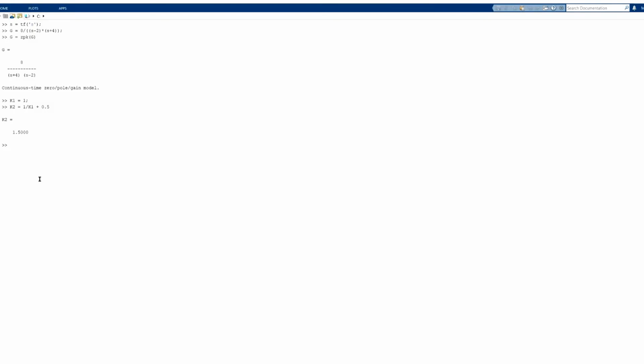But if I move on with this one, then I have actually the situation for A. So I now have A equal to feedback with K1 is 1, K2 is 1.5, and I have this expression. Now, if I want the total transfer function T, which is again feedback, it's the same configuration. Now I have in the forward path the A, which is multiplied by our integrator 1 over S. We have seen this, and then in the loop I have only unity gain, so it's just 1, and I have again minus 1 for negative feedback. And this system, if you look at it, is now the total closed loop system.